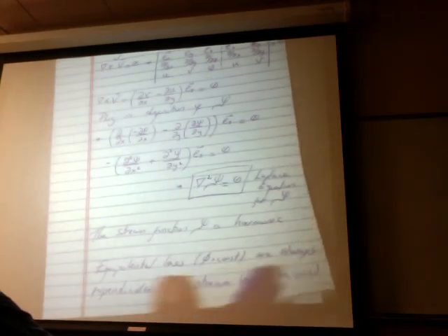Furthermore, after this came conformal mapping. If you can find a solution for a fluid flow in a circle, for example, then you can use conformal mapping to change that circle into something else, and then the solution applies in that other plane, the transformation plane. That's how they came up with solutions of fluid flows on airfoil types of shapes. So the first attempts to solve fluid flow problems were done by this particular set of arguments.